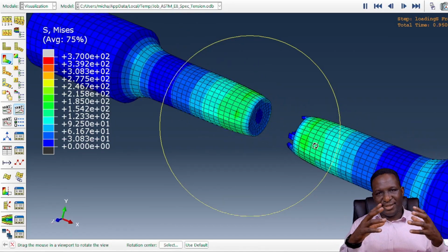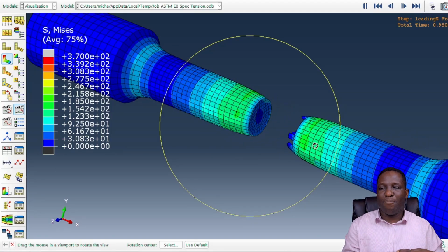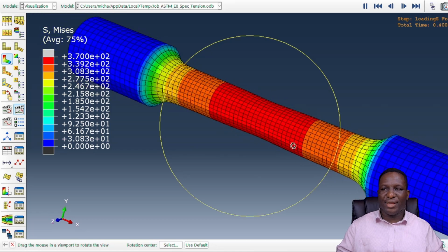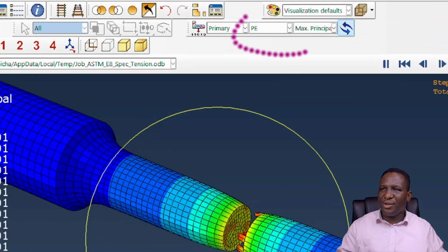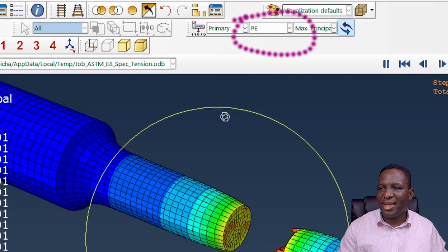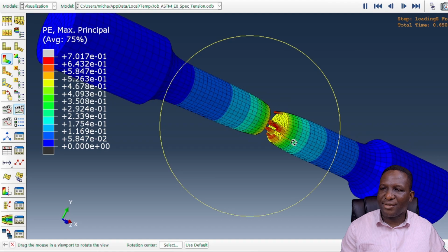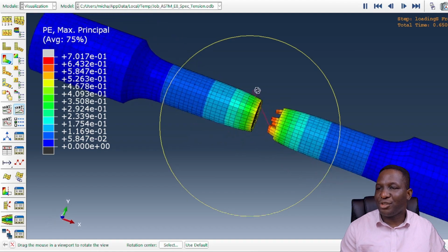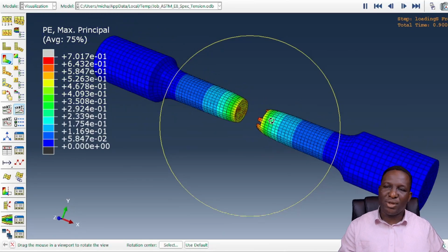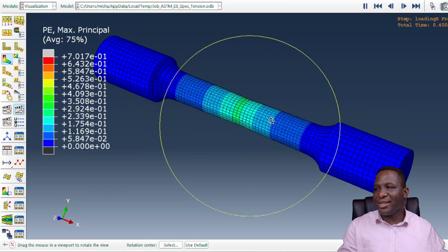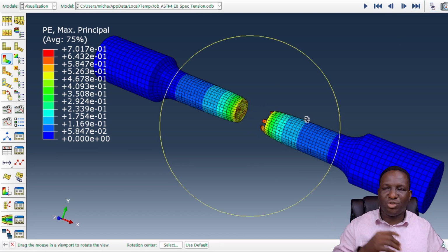And so everything around this setup is perfect, because we have set it up properly in the way it should be. This is an excellent set of results that we're happy with, and it captures everything that we need. If we look at the plastic strain, that's what you see here. Right in the gauge section, the plastic strain builds up, and then it fails plastically, and you get a plastic deformation in this material, and it looks really good. The reason why this is so is because we have done it properly by calibrating it properly with all the parameters required.